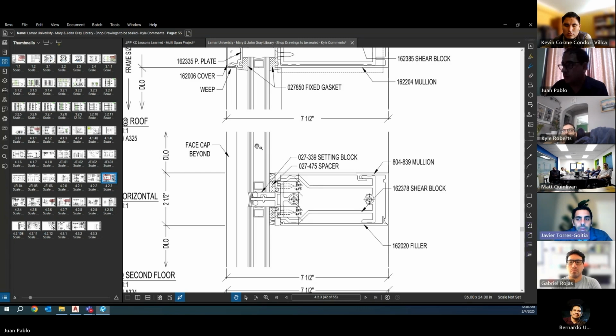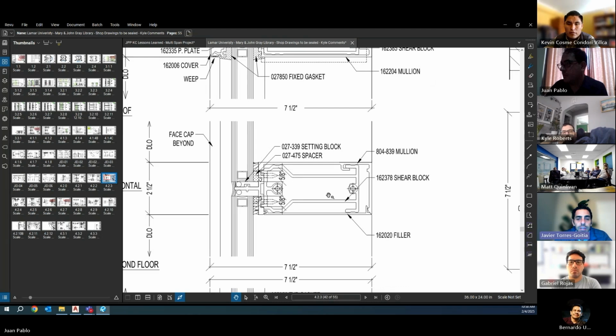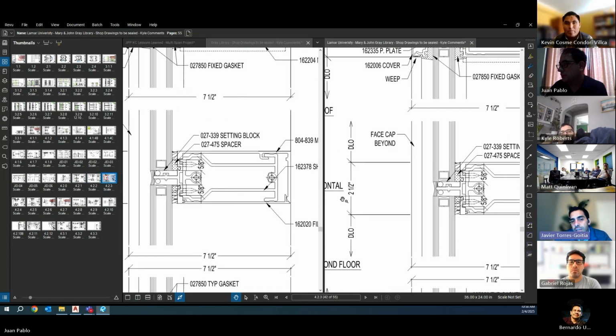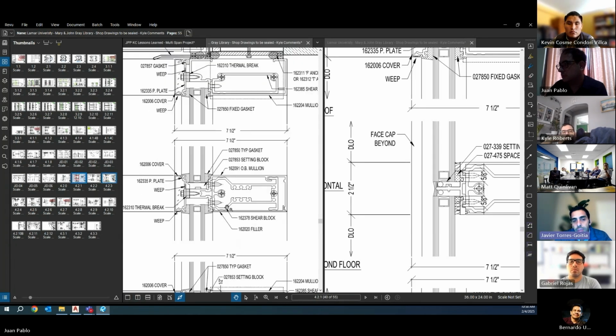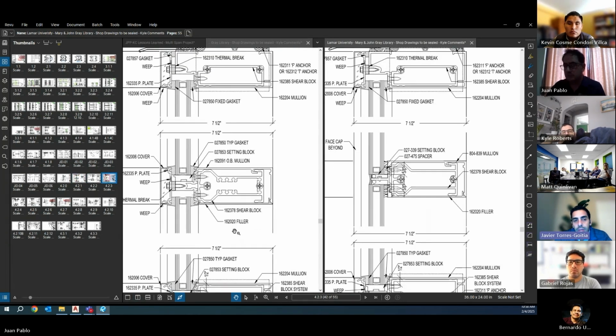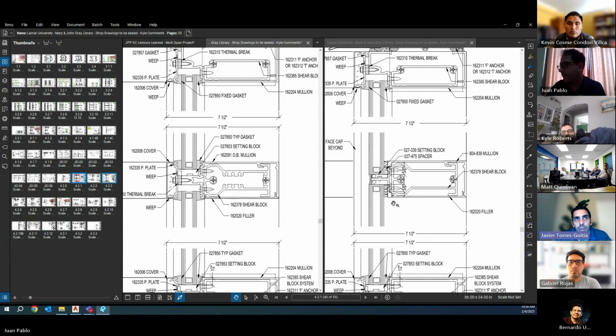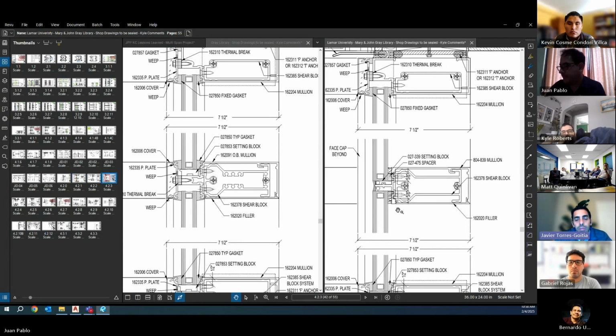Right. Yeah. When you do the hard splice route, think about the whole frame moving as one huge piece. So there's no differential movement within the parts of the frame. The sealants are not tearing, the glazing pockets are not being maxed out. If the sill moves up or down, the entire frame moves up and down.